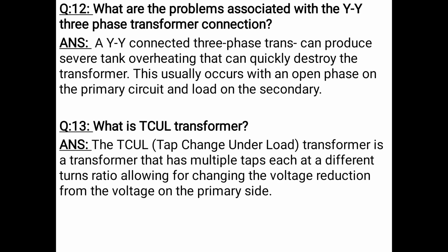Number 13. What is a TCUL transformer? Answer: The TCUL, tap change under load, transformer is a type of transformer. It has multiple taps, each at a different turns ratio, allowing for changing the voltage reduction from the voltage on the primary side.